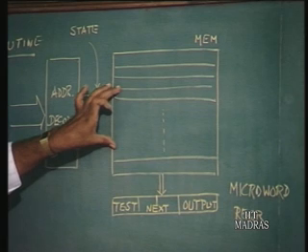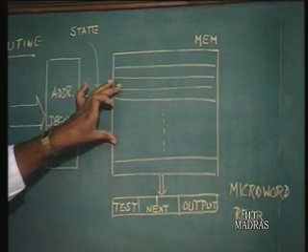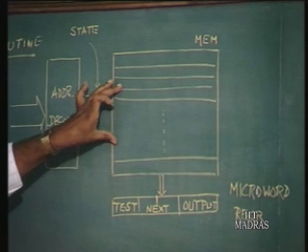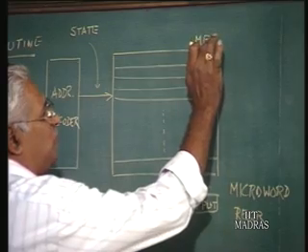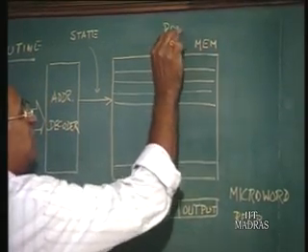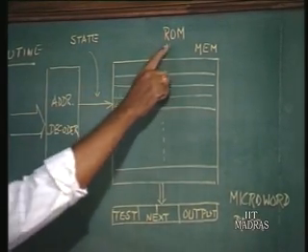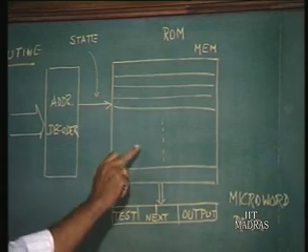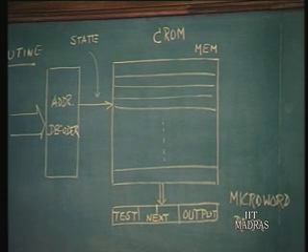Once you design a processor, these memory contents need to be only read, right? Because its behavior will be frozen once you have these codes, correct? Then you would find that this memory is nothing but a read-only memory, because subsequently only the contents of the memory will be read. Specifically, since it is used for control purposes, it is called CROM or control read-only memory.